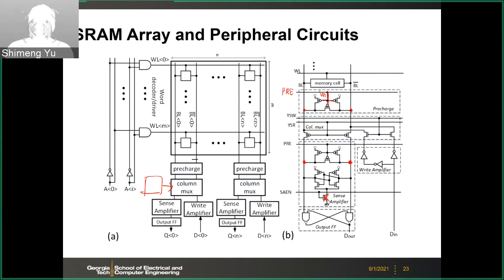So this latch in the middle is in the floating state, because there is no path to the ground. Therefore, the latch here is floating. Since they are floating, you can have both those 2 loads be at VDD, because this is disconnected from the ground.